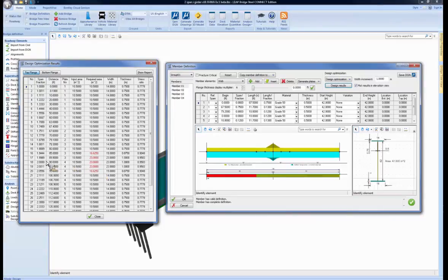So for example here, kind of mid-span, it's saying it still needs about 23 inches there, and I could do a jump all the way up to a 23-inch wide plate at 1 inch, or maybe use some other plate size there. So again, that's going to affect two different plates right there. So what I'm going to do is I'm going to come in here and select those two plates. So I'll go to top flange, and that will be these middle two plates right here.